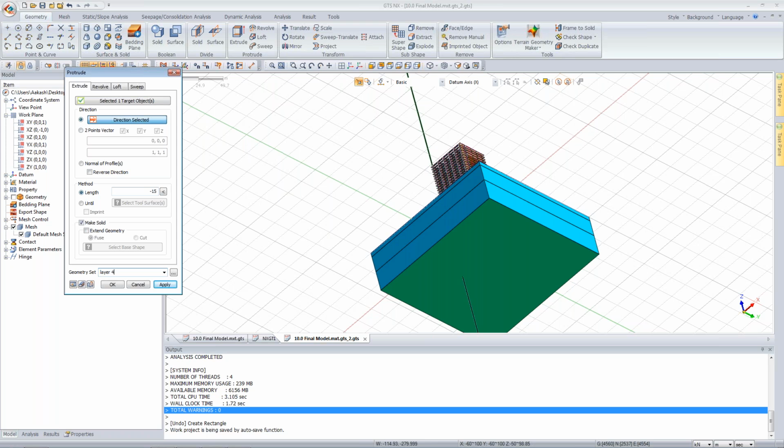are some basic first-hand rules, but what I believe in is after the analysis is run, the settlement contours at the corners or at the bottom edge shouldn't touch the edges or the bottom. What I mean to say is that you should get approximately 0 or nearby 0 displacement at the bottom at the corners. Okay, now there are basic rules like 2 to 3 times B, where B is the area of concern. But the best part is after you run the analysis, you check the results and make sure that the settlement contours don't touch your outer profile.